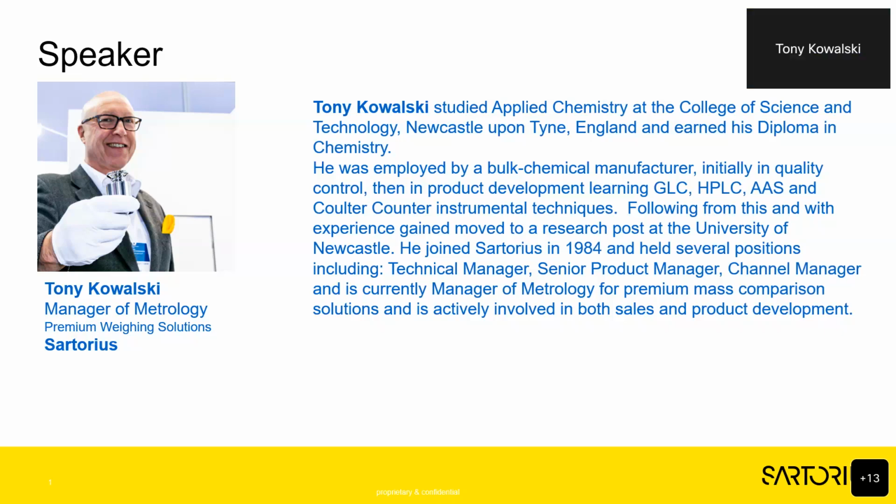E0, or sometimes they're called RS, are really needed if you're looking to calibrate class E1. We did have one customer who bought a mass comparator from us with the integrated software, and he was trying to calibrate E1 weights with E1 references.